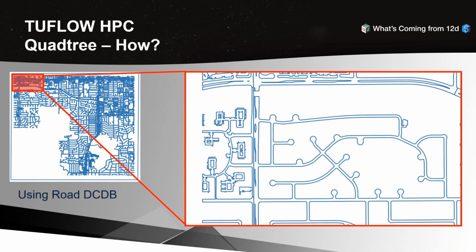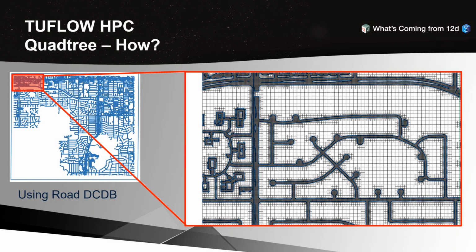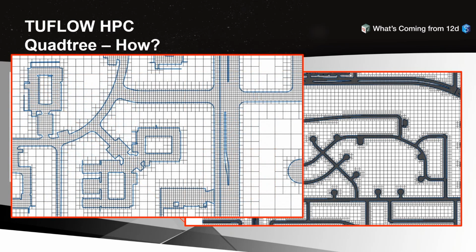It has pretty big implications when you're dealing with big urban settings. This one here is Phoenix, Arizona. We built this model across the entire area, took the roads network layer, applied a level 4 value to the roads layer, and TUFLOW automatically created this mesh for us, stepping from level 4 out to the coarsest resolution. And it also automatically assigned all the different boundary conditions from that original single resolution model and also the 1D, 2D linkages for us.